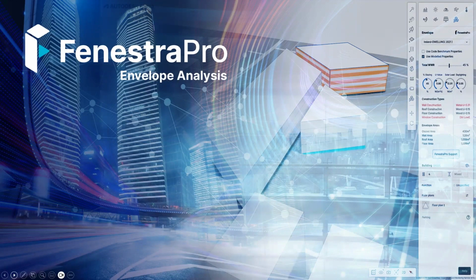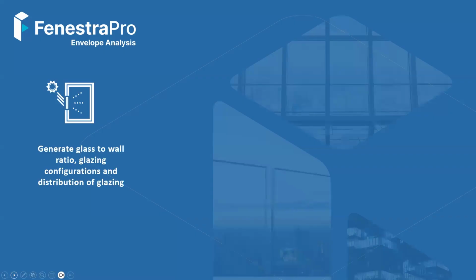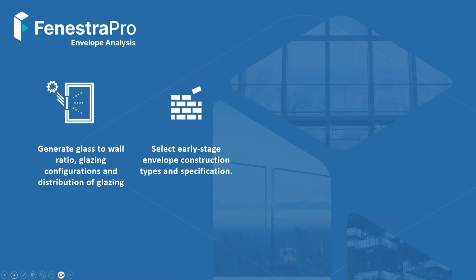So we provide a number of tools relating to what Cesar was talking about. We provide FenestraPro Envelope Analysis for Forma, which is an extension for Forma. I'll go through it in a second. Within that early stage conceptual environment of Forma, it allows us to generate glass-to-wall ratios, understand the impacts of them, configure that glazing, and distribute it around different orientations or different facades relating to sun paths or shading from surrounding buildings or the urban environment, etc.